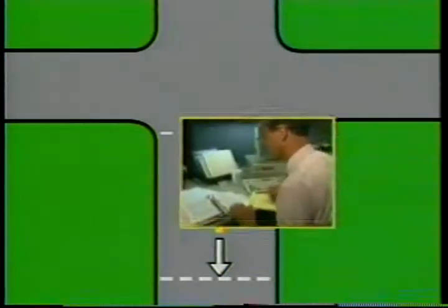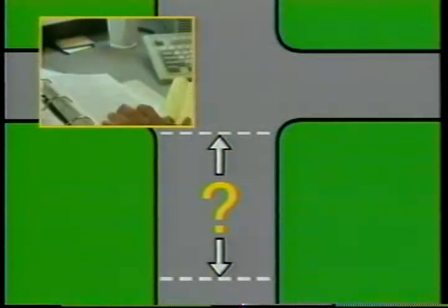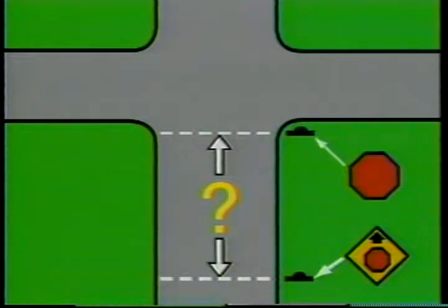To determine the location for a warning sign, an engineer should consult a table. The table is based on required driver responses, such as recognition, detection, and required maneuver. It considers a range of driving tasks encountered at various speeds. By matching the variables, the engineer can determine the minimum placement distance required.